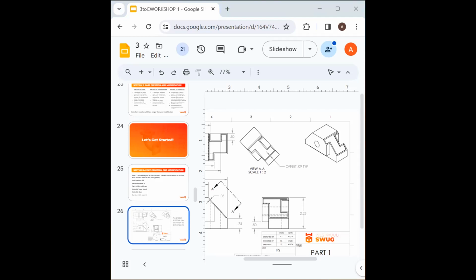This has a coincidence, so it won't let me do it. So I have to delete that in order to be able to edit this dimension. And then this one, the same thing applies. I needed to make it coincident to a specific line, or make it collinear. And the same thing goes, I'm going to extrude it all the way to the other side. So now I have that lip missing from my drawing.